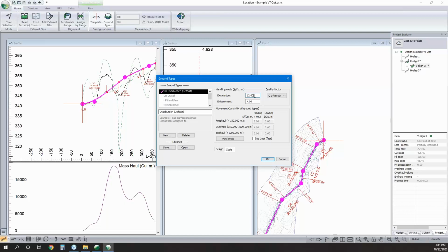If you're an owner-operator looking to design your own roads that you're going to build, in that case I'd probably derive these costs either based on historic data for how much specific tasks have cost me in the past, or base it off of production equations and rental rates. And if you're going that route, I always relied on the CAT performance manual to get reasonable cycle times.